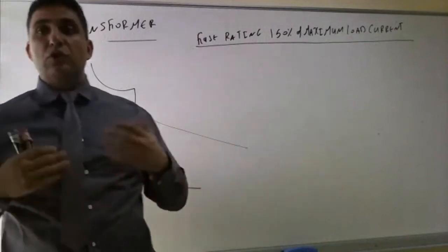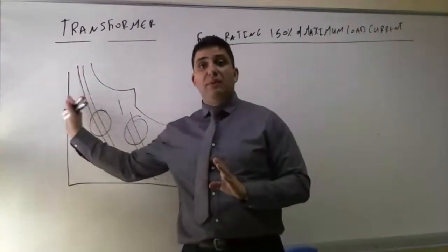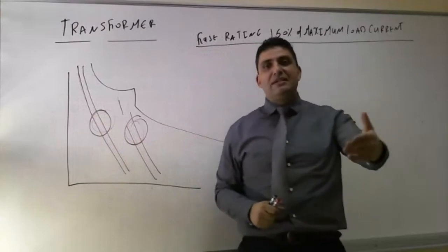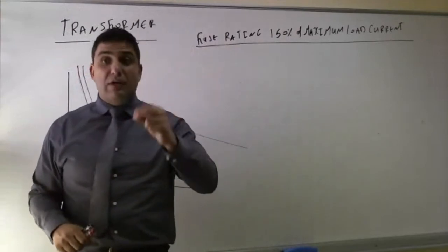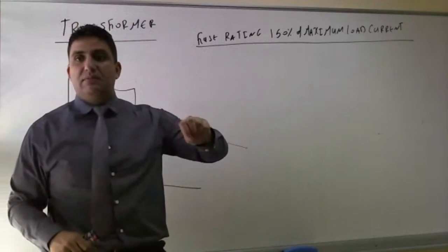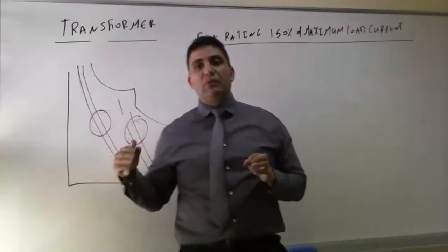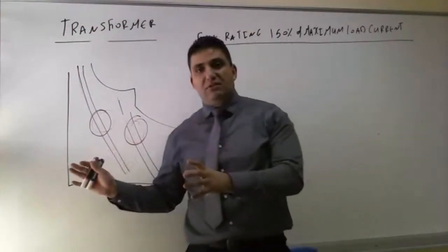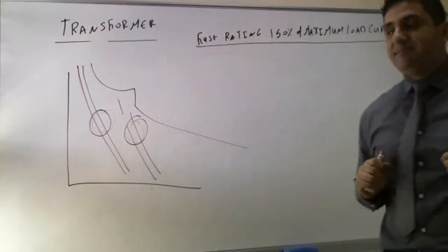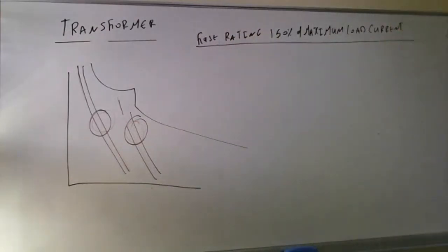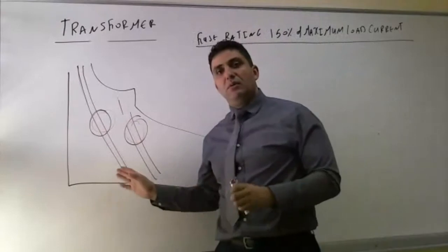And remember, when it comes to quiz, homework, or exam, I can ask questions based on a little bit of theory. So I can ask you, please determine the type of protection required for this transformer if it is located in a standard, normal area, and its capacity is 7,000 kVA. You should be able to tell me the typical protection required for this transformer is the induction disc over current relay. Like I said before, you already covered the time delay, instantaneous and time delay over current in the previous chapters. We are not going to cover it.